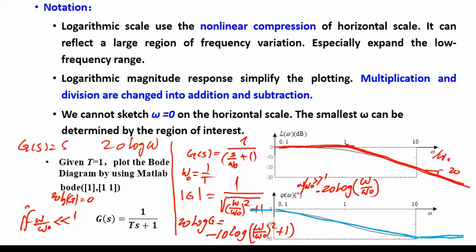So we again make an error of approximately 5 degrees, right? Okay. And now when you curve it, start from 0, go to minus 45 and back to 0 again at one decade higher frequency, you get a fairly accurate plot.